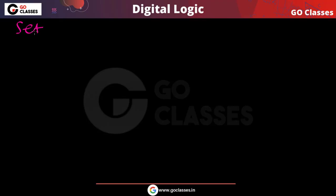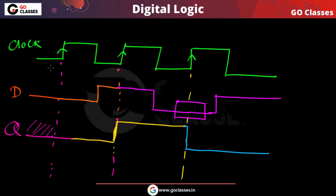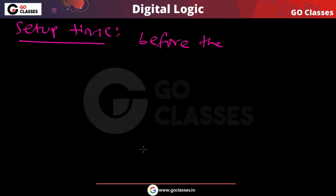This is the definition of setup time. Let me explain. Setup time basically means, if your flip-flop is positive edge triggered, then before the rising edge. If your flip-flop is negative edge triggered, then before the falling edge. So before the triggering edge, let me call it the triggering edge, comes,